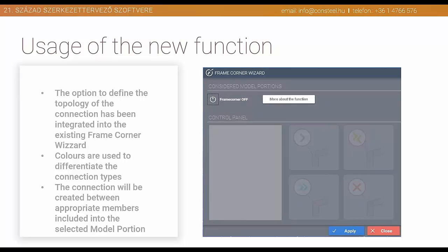These criteria are that the elements which are connected must have a moment-bearing connection between each other. It means that the degrees of freedom of the selected elements must be continuous. They must both have I-sections, which can be welded or hot rolled. Their webs must be located in the same plane, and the angle formed between the two members must fall within the range of 90 degrees plus or minus 30 degrees. So these are the conditions.